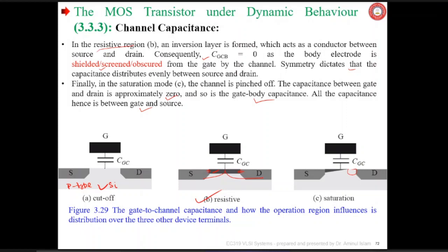It is not a conductor like aluminum or copper, but it is a semiconducting material, P-type. Remember that even intrinsic silicon has resistivity in between conductor and insulator. Here we have doped it with P-type or trivalent dopant, so conductivity has even increased above the intrinsic silicon. Then why are you telling that there is no conducting path from source to drain? Could you understand my question?